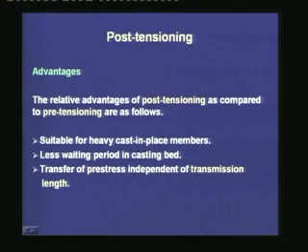Another important advantage of post-tensioning as compared to pre-tensioning is that the transfer of pre-stress is independent of the transmission length. Last time I mentioned that in the pre-tension members, the transfer of pre-stress occurs along its length, especially towards the end, which is called the transmission length or transfer length. The bond between the steel and the concrete has to be good to transfer the pre-stress from the steel to the concrete in a pre-tension member.